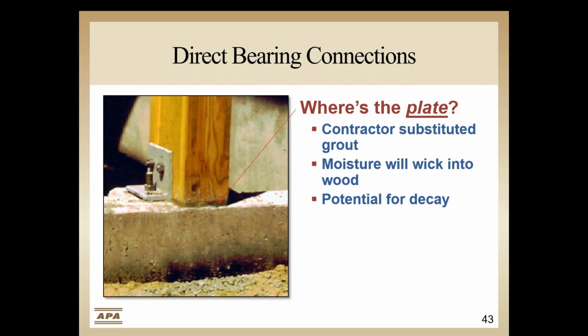Even when we get all of our detailing correct, sometimes decisions are made in the field. And by the way, the designer of this detailed a loose steel plate. However, the contractor felt grout would still work just as well. However, grout, like masonry or concrete, should not be in direct contact with the wood.